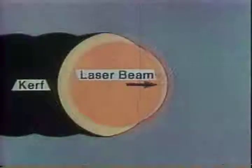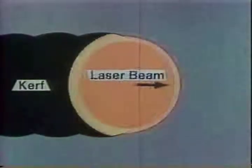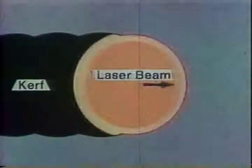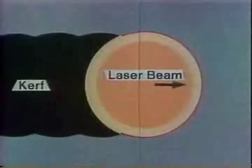After ignition, the reaction front progresses radially at higher speed than the beam travel speed, and finally the reaction is interrupted at the edge of the yellow circle. But the beam itself is traveling at constant speed. When the orange zone contacts again, reignition takes place instantly and reaction develops rapidly. In low-speed cutting, these characteristic processes are repeated periodically.